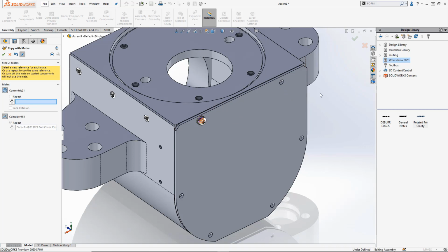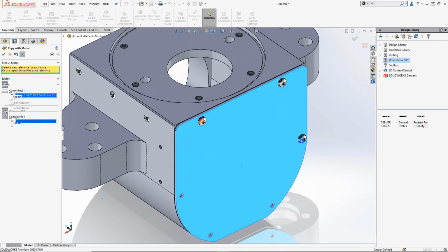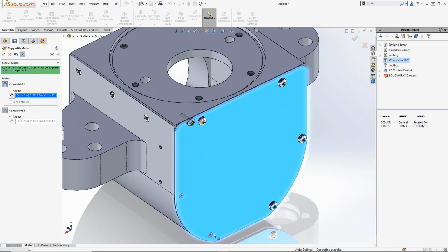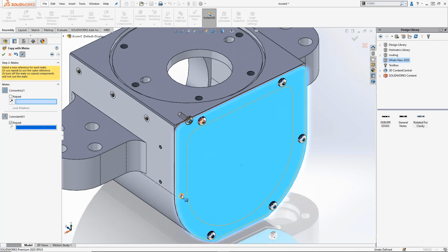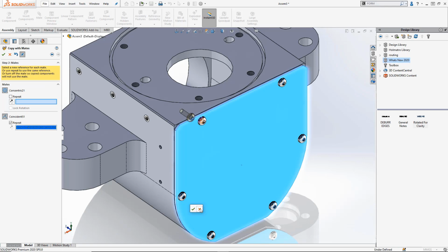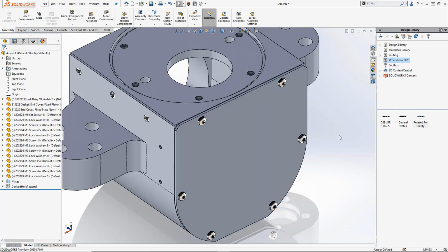So all I need to do now is go around selecting my new cylindrical reference for the concentric. So we'll select that face, and then I'm just right clicking to move on to the next one. So you can see very quickly I can populate my assembly with all of those instances. I'll use the D key to bring confirmation corner next to my cursor and exit the tool.